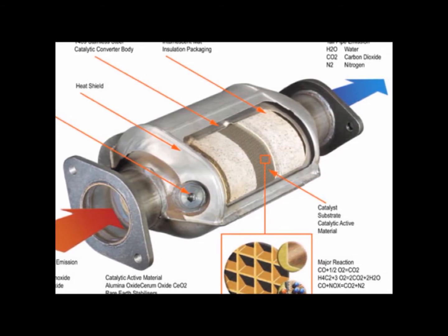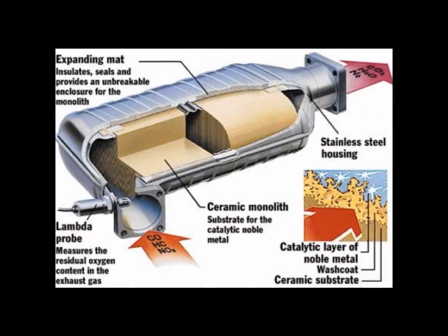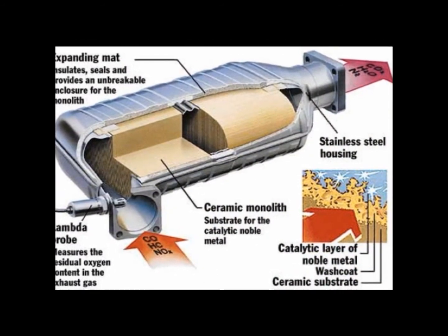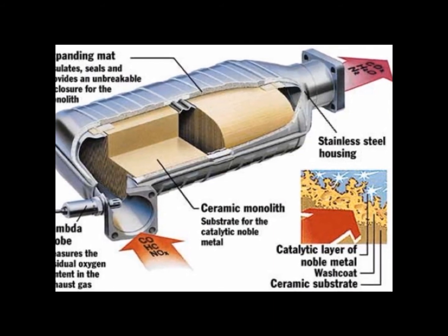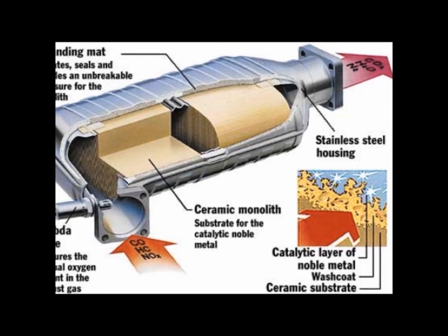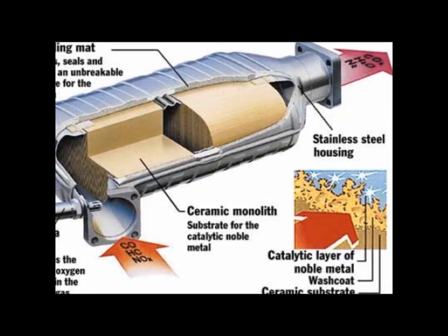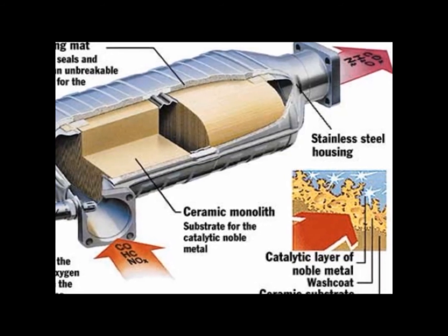Most present-day vehicles that run on gasoline are fitted with a three-way converter, so named because it converts the 3 main pollutants in automobile exhaust. An oxidizing reaction converts carbon monoxide and unburned hydrocarbons, and a reduction reaction converts oxides of nitrogen to produce carbon dioxide, nitrogen, and water.